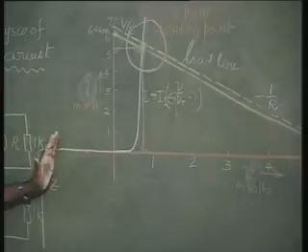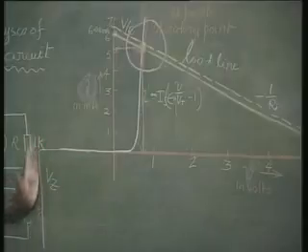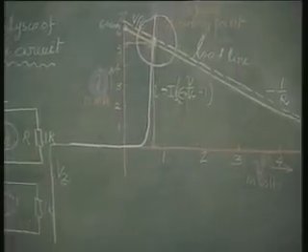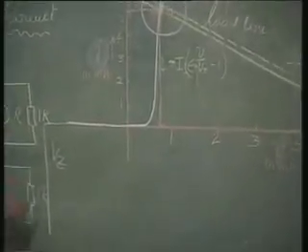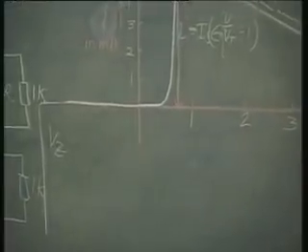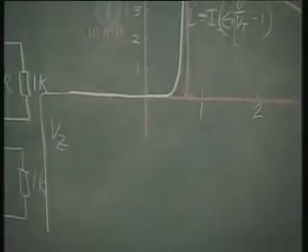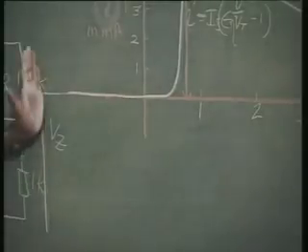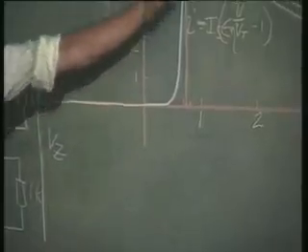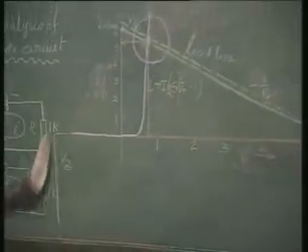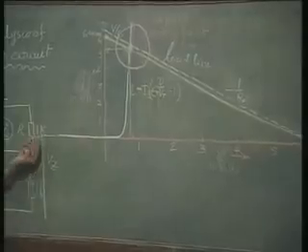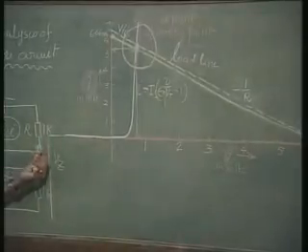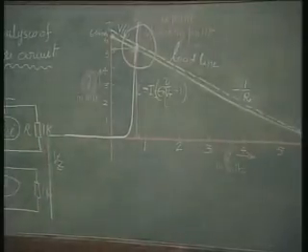But when it is being used as a Zener diode, this is precisely controlled, and therefore you have Zeners which are available from a few volts up to hundreds of volts. This breakdown region, you can see, is similar to the exponential current increase. So, the current increases drastically for the same voltage. That characteristic of the diode can definitely be used.